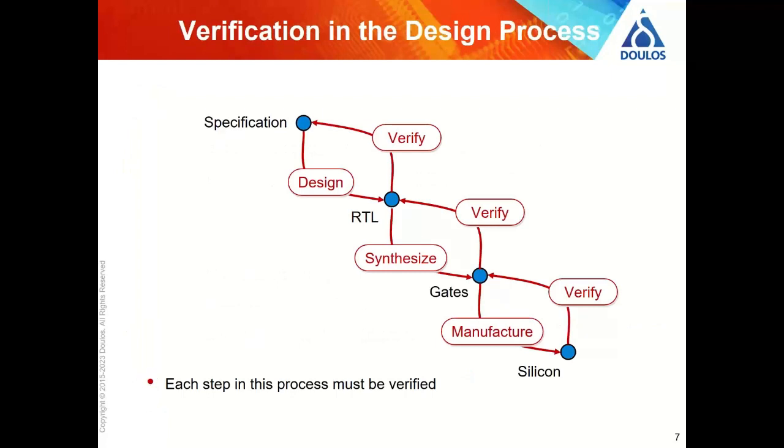So what is verification actually doing? Where is it applied? If we take a typical design, the starting point might be a specification. We write our RTL code, maybe in VHDL or whatever language you prefer, and synthesize it, and we get a gate level description. If it's a chip, then that will go on to the back-end process until we get to the master layers. Verification is required at each of those steps. It won't necessarily be the same approaches, but we still have to verify it.